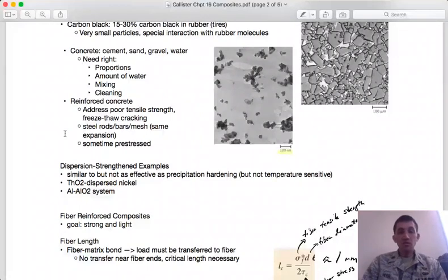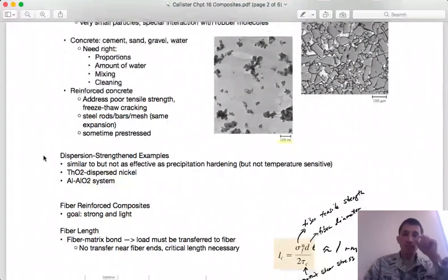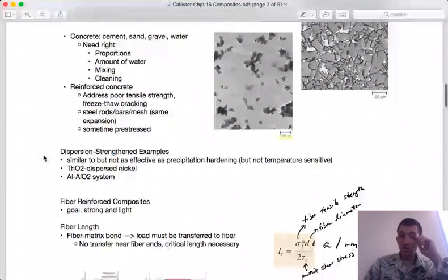We've seen this before in things like surface carburization and shot peening, and you see it in tempered glass too: if you have a brittle material and you can somehow put a compressive strain on a ceramic material, that residual compressive strain will act to push cracks closed as they're forming. And so pre-stressing and reinforcing concrete can do a similar thing.